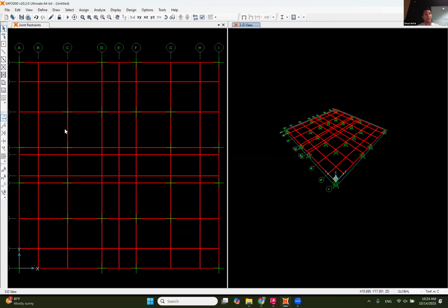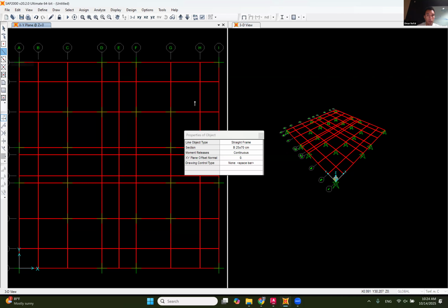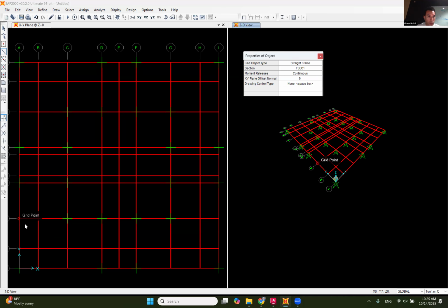So why did I make this section? Because right now I'm gonna draw a beam and pick this section. By the way, this section is temporary for now. I'm gonna draw at the location of the walls. I'm gonna draw one here, and I'm gonna draw one here. This section is a beam section that is really, really stiff, and we are gonna find out how we can make this section act like a wall. All I need from this is a reaction at the supports that are here.